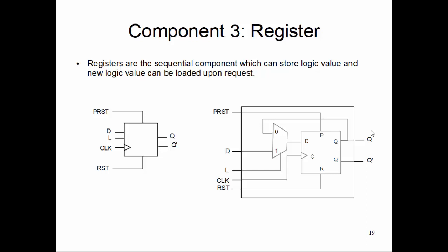And if we use a flip-flop as a storage device, that means upon the active edge, let's say it is a positive edge trigger flip-flop, upon the positive edge all the modules B, C, D will store that data. There is no way for module A to send data selectively to module C, for example, or at some other time instance to module D, or both module B and D but not C, right?